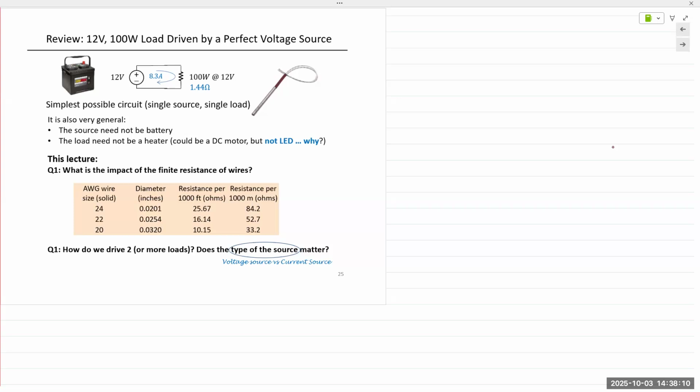But let's say you take a HDMI cable and you run it over 100 feet. So you take a 100-foot long HDMI cable, what do you think? Is it going to work? Probably not, because there are digital signals. You transmit digital signals that are very small voltage or current over very long distances. The resistance or the inductance or the capacitance of that cable is going to interfere with those very small voltages.